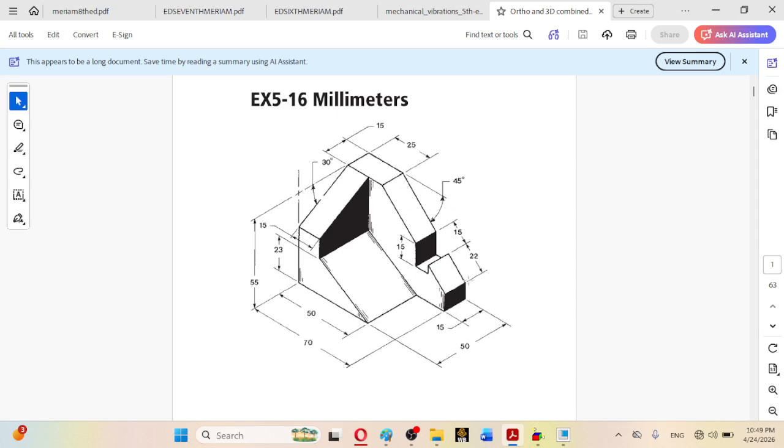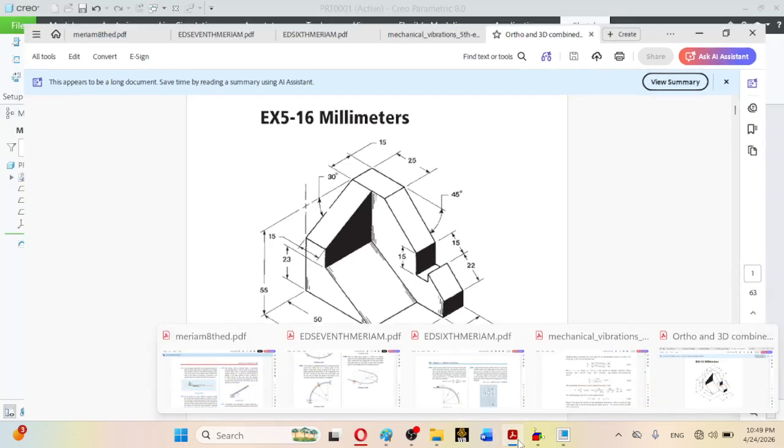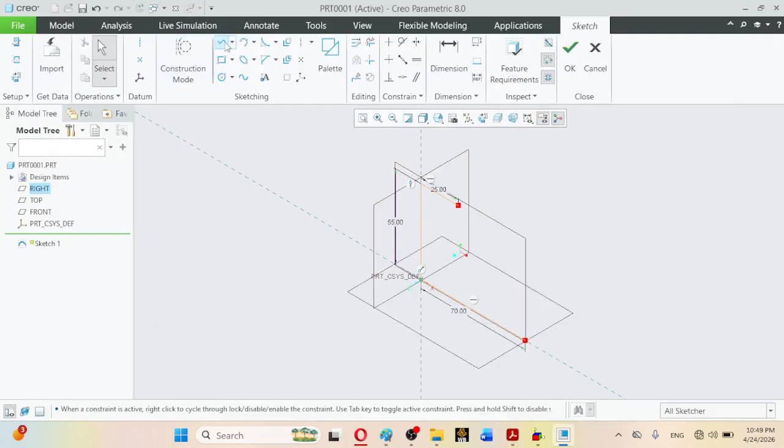And after that what you will be doing, this dimension is actually not yet known, but you will just be drawing an arbitrary line segment in the vertical orientation from here. For example, you will be selecting this point and simply clicking on it. When the vertical constraint, remember the vertical constraint must be shown, so just make an arbitrary line here like this.